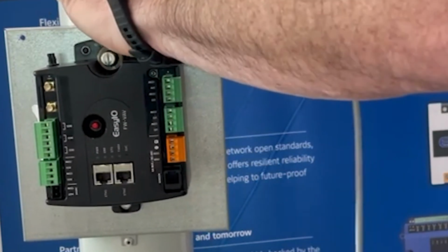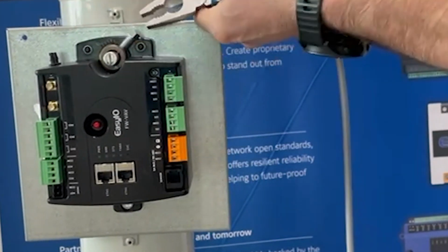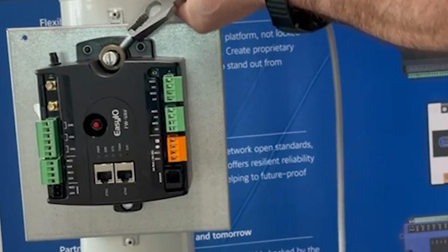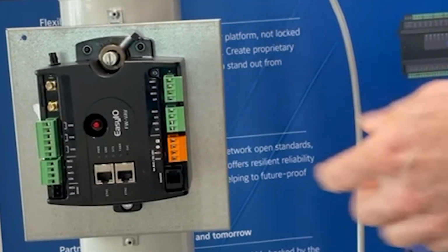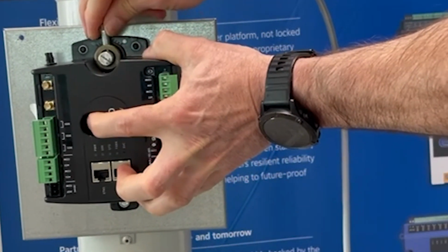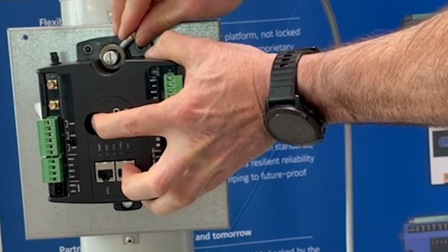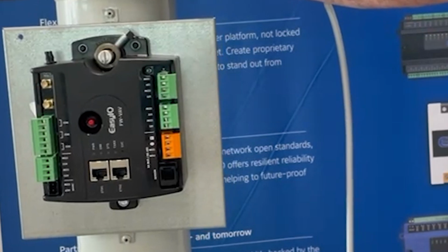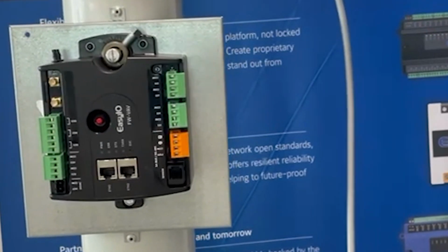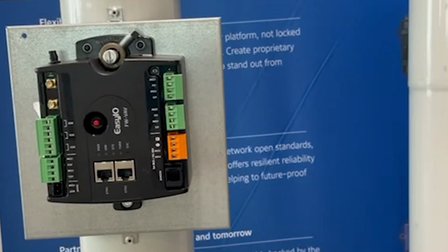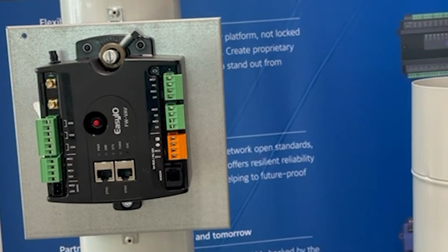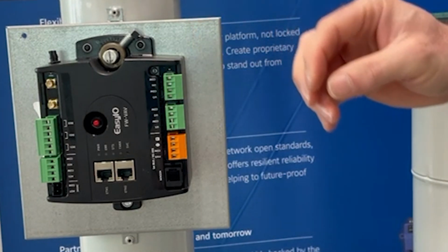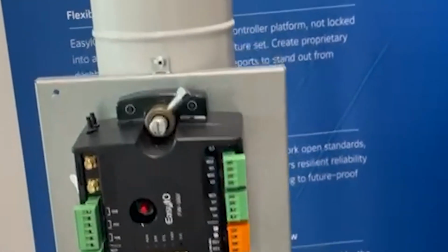Now when the motor steers to 100%, it turns to the right, and when it is fully open the motor can't go any further because it is mechanically against the end of the motor. If it is now steered closed, it can't go any further, because it is mechanically against the end of the air valve. So this way you are assured of a correct open and close position. If you don't do this properly, the valve will close again the moment it is steered open.